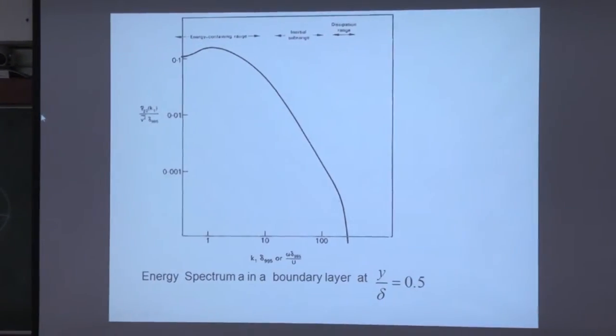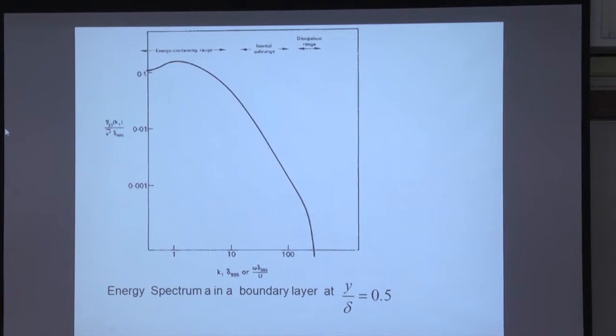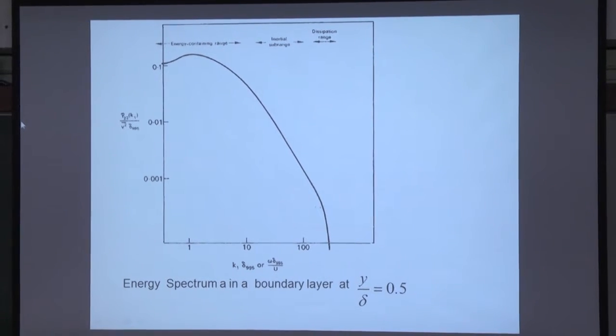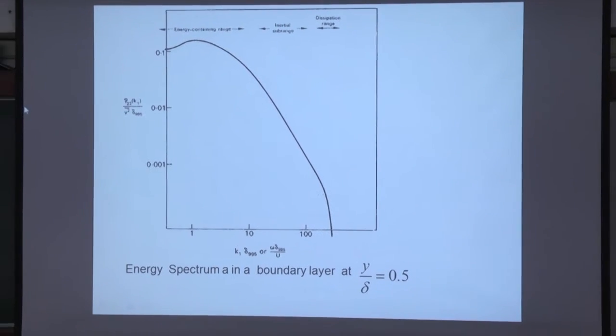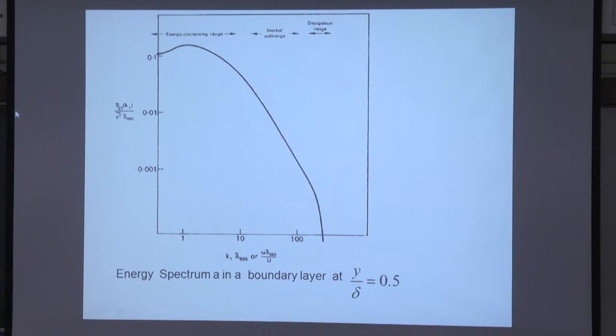Okay, so I told you earlier, the mean velocity description, you can break it into an outer region and an inner region, right? The outer region which is inviscid, and the inner region which is viscous, very close to the wall. There's a region where you expect an overlap which partakes of the nature of both these regions. Likewise, here there is this outer region where it's all inviscid, the larger eddies, whereas here these are smaller eddies which are as viscous as they get. The expectation is that there is a range of intermediate eddies which have a similar behavior in the spectral space, right? So for that region, if you now write, this is a celebrated result of Kolmogorov.